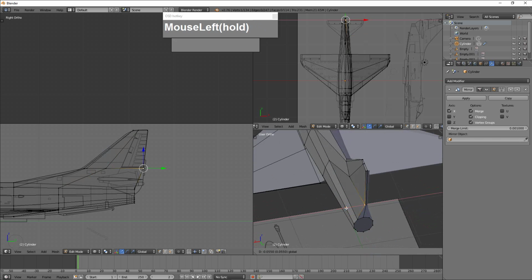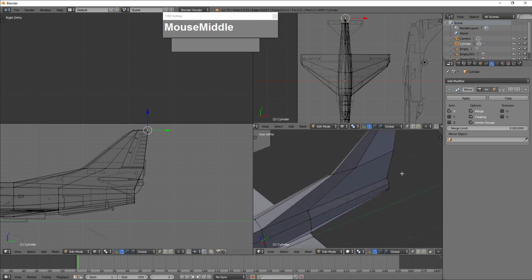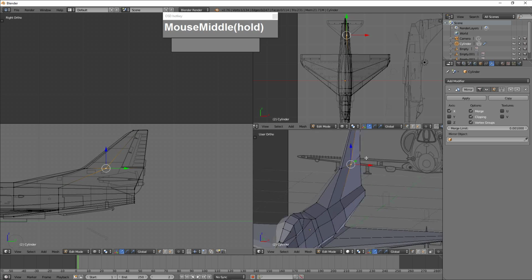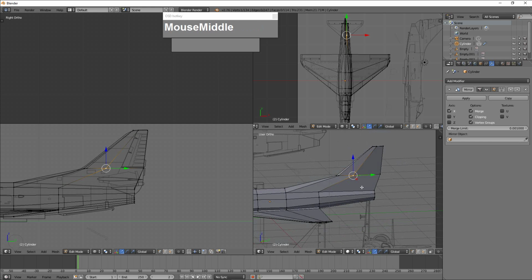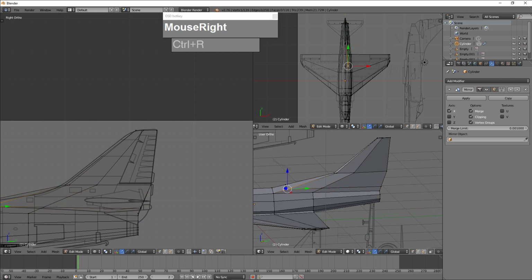Again, the dorsal fin also has an airfoil shape. I'm going to insert one more edge loop right near the base here to tighten it up. So Control R, insert one edge loop right at the corner here. And then this one I can pull it back and then push it inwards from the top.